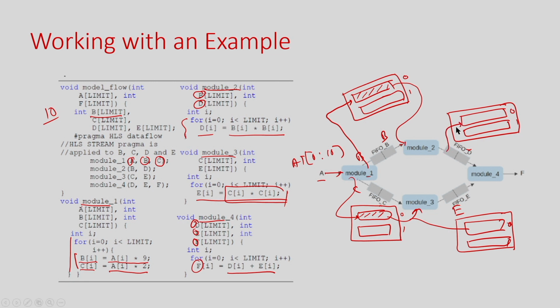At the same time, from the 11th clock, module 1 will take the next set of data, right. So, the first set of data is already processed, now it will take the next set of data and start writing the data in the next buffer, right. So, it will now start writing into the next odd buffer. So, this is say C2 and this is also say B2. You can understand that after the 11th clock, modules 1, 2 and 3 are now running in parallel.